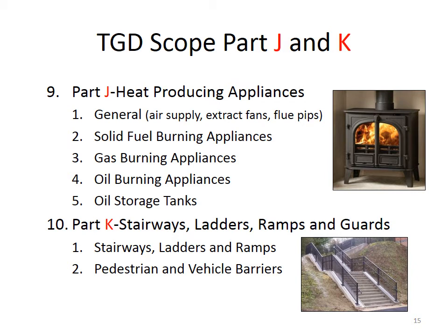Number 10 then is part K, which covers stairways, ladders, ramps and guards. This would be stairways, the height, the angle they should be at, the way that every step should be the exact same height and the exact same depth. The rise is the term given to the height of each step, and then the going, which is the length of the step.